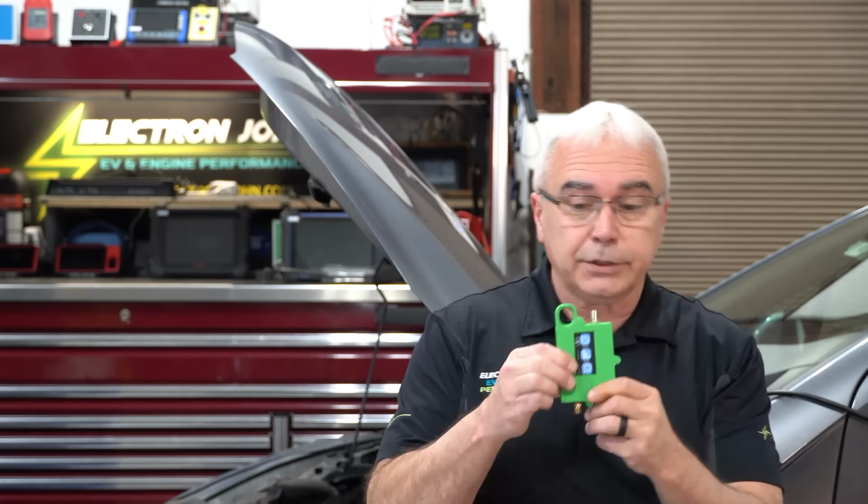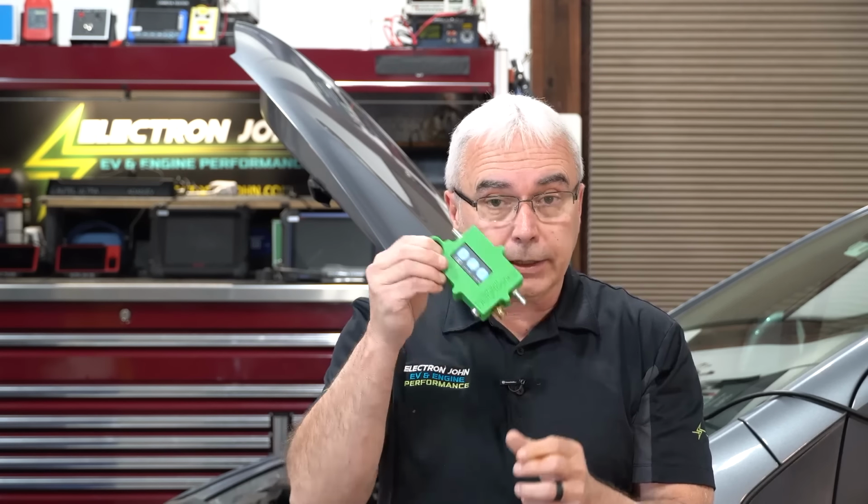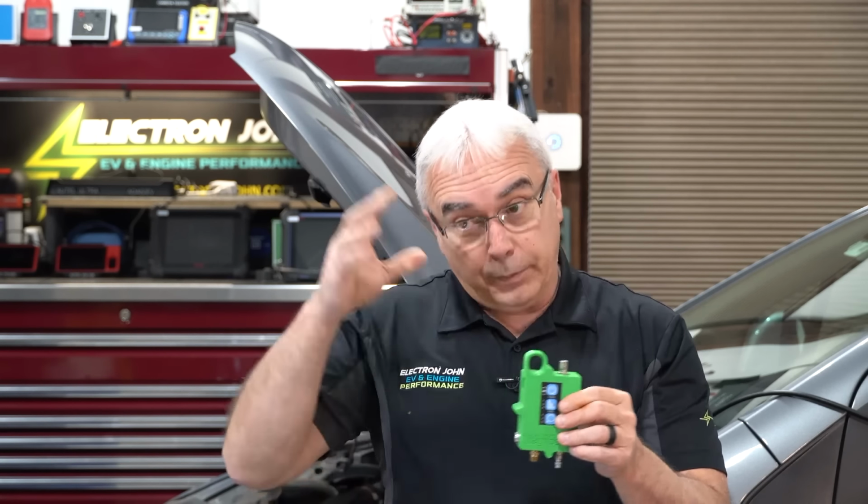The benefit to using an in-cylinder pressure transducer is that technically I do both of those tests electronically at the same time by going directly inside the cylinder. I can see the valve train operation, plus I can see the overall compression. So that's a shortcut that I could choose to do if I wanted to.